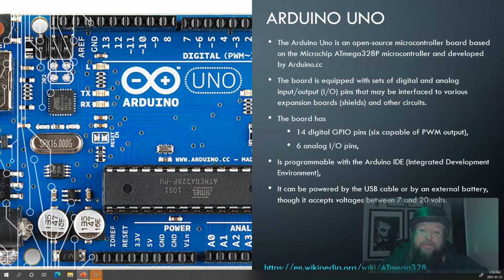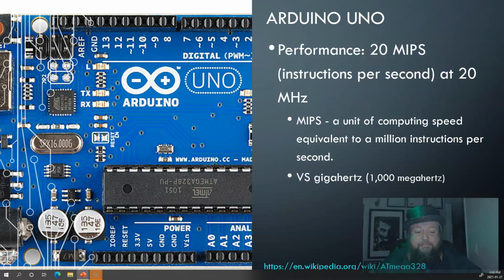And you have the Arduino IDE for development, and we'll get into that and probably see more examples when you come to the physical videos, not as much for the simulator because it has its own separate tool that you use for that, but with a similar language. You have a USB cable which can be used to power it and transfer programs to it, but you also have other ways to provide power. That is just used for power and data. There are ways to power it from 9 volts and other power sources. There are multiple different ways you can power it, and you just have to look that up.